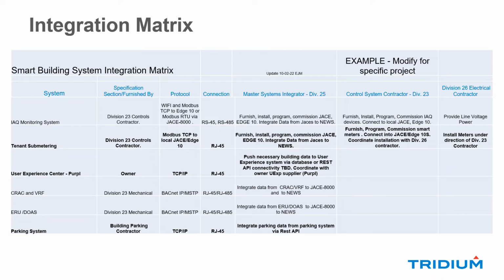So Division 23, because these are smart meters, had to do some commissioning directly at the meters. A little bit of software had to be touched there. And then Division 26 certainly had to install the meters correctly, wired up and installed close by the switchgear.